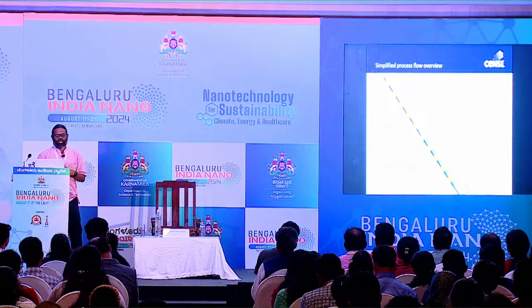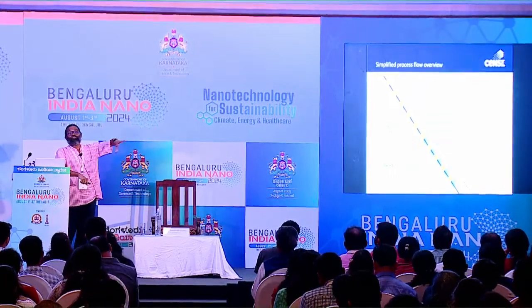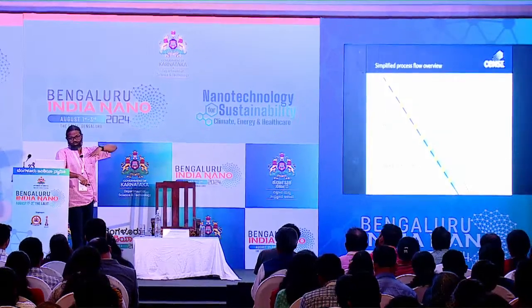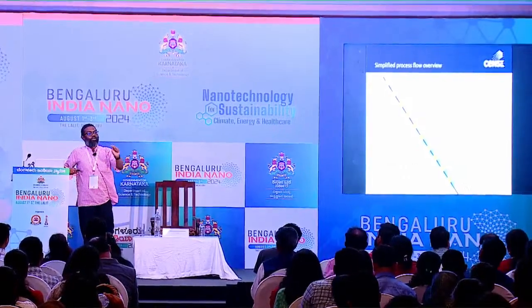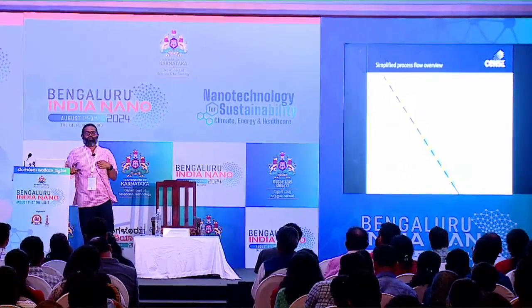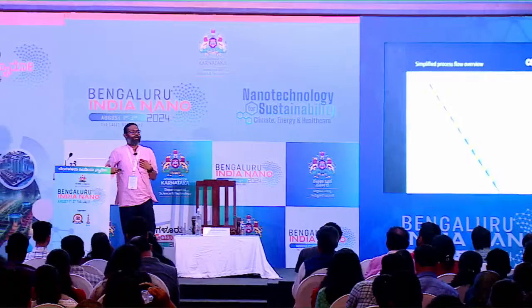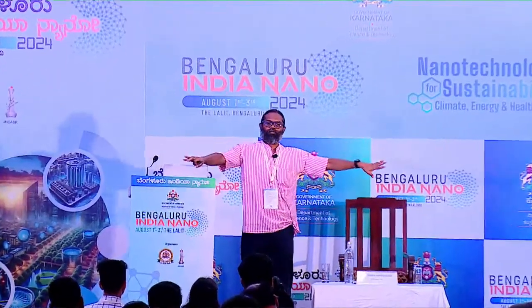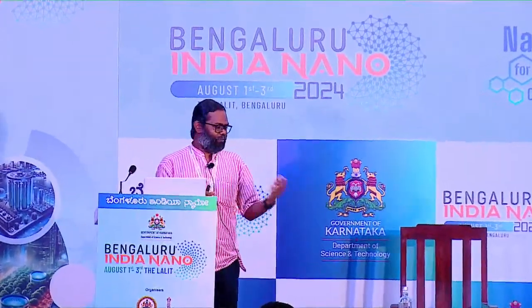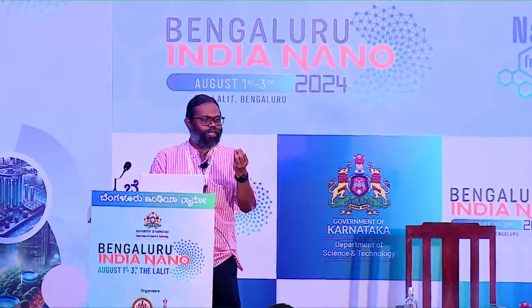The other way we also look at it is that in the front end we can use high temperature processes before the metals come in. When the metals come in, you should not heat up your chip, or rather your wafer. Why? Because metals have a low melting point and they start to flow, okay, and you will have a short. And that's one of the reasons why all your processors are actively cooled. If you don't cool it, the temperature rises above 500 and it's gone, okay.